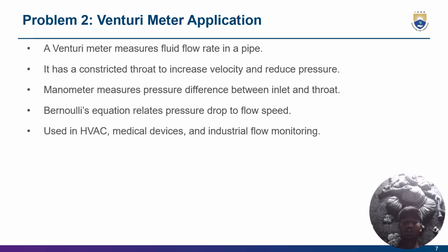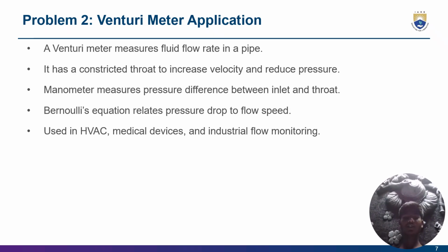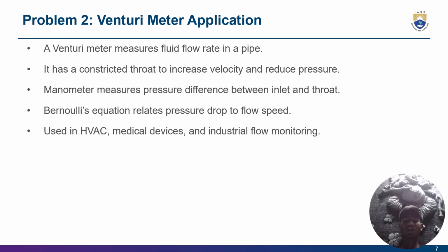Venturi meter application. A Venturi meter measures fluid flow rate in a pipe, as constriction causes increased velocity and reduced pressure. It measures the pressure difference between inlet and throat. Bernoulli's equation relates pressure drop to flow speed, used in HVAC devices.